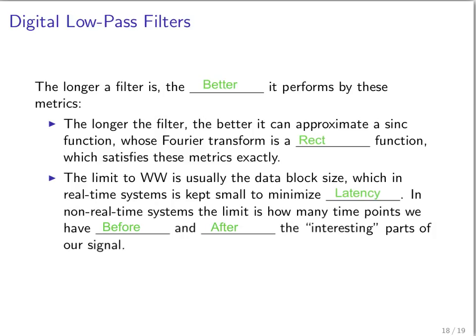Earlier, we alluded to the fact that moving average windows or any other kind of digital filter will chop off samples at the ends of your signal, and so we have to have enough time in our signal that is uninteresting at the ends, that we don't care about deriving any quantitative information from, to be able to throw away so we can use a longer filter. Okay, but generally speaking, the longer the filter, the better the response.